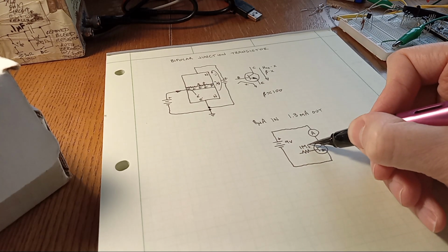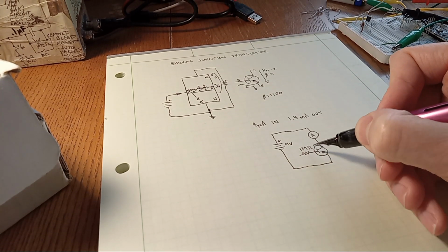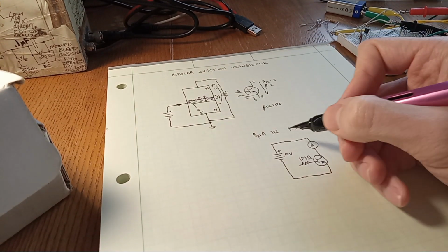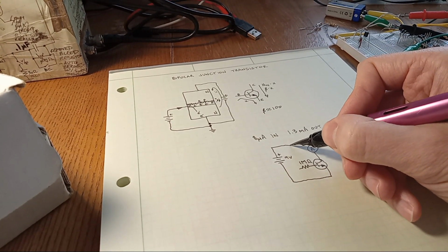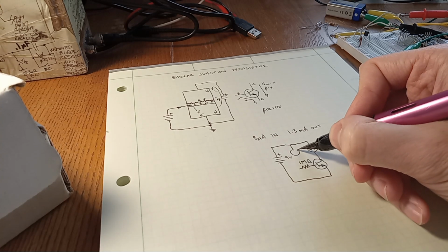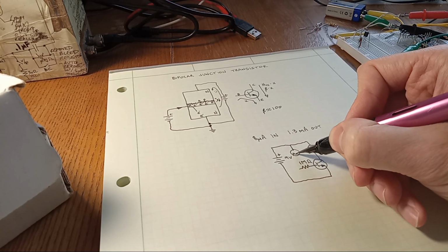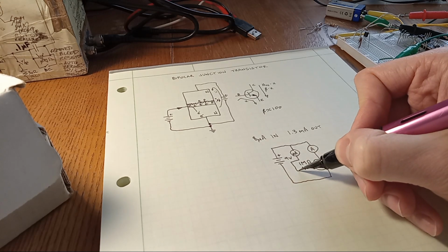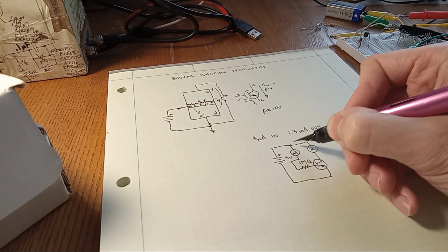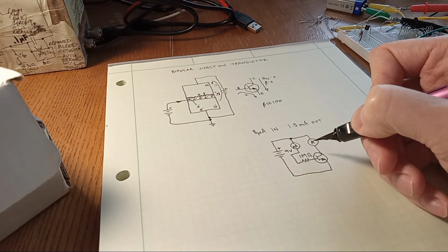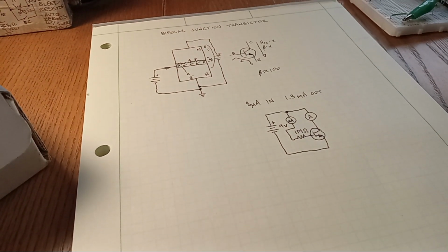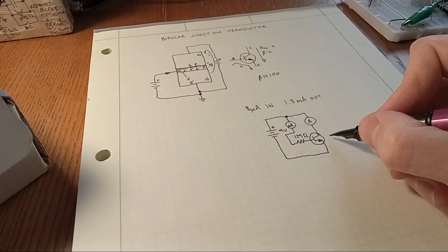Until you feel comfortable guessing at correct resistor sizes, include guard resistors in line with your components so you don't burn anything out. Then there was a second microammeter. I think for the standard drawing it would just be a circle with an A. The mu is, I think, non-standard, but people would tend to know what it means, I hope.